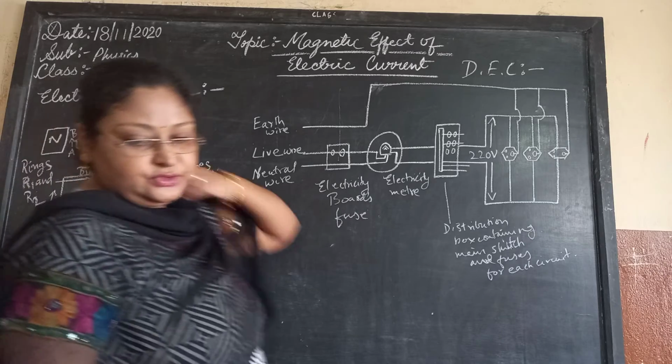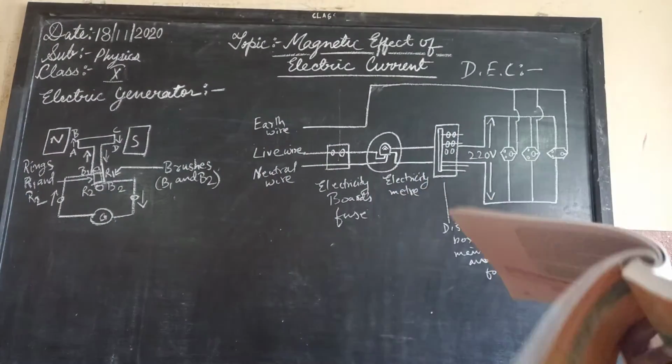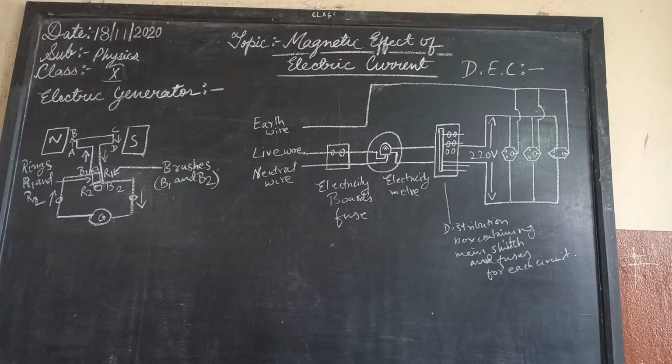The electric generator consists of a rotating rectangular coil ABCD, placed between the two poles of a permanent magnet. The two ends of the coil are connected with the two rings R1 and R2, and the inner sides of the rings are made insulated. The two conducting stationary brushes V1 and V2 are kept pressed separately on the rings R1 and R2 respectively. The two rings R1 and R2 are internally attached to an axle. The axle may be mechanically rotated from the outside to rotate the coil inside the magnetic field.